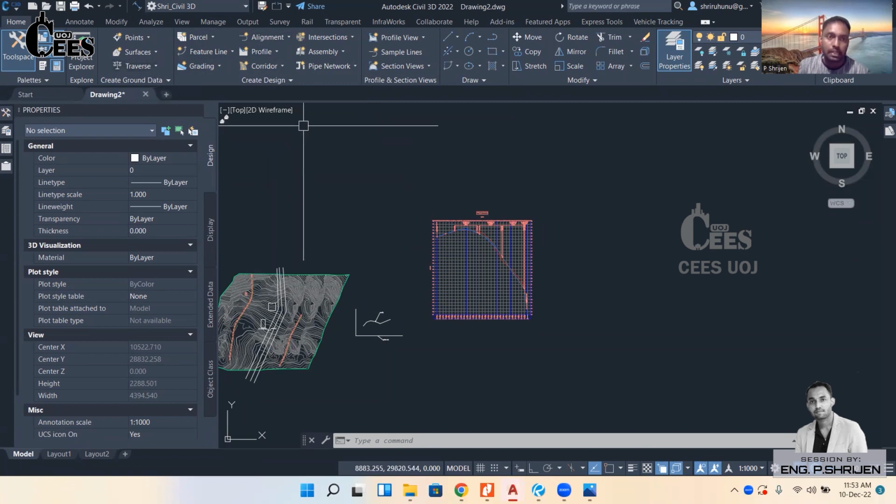By using the survey editor, the traverse works and gives the information by point. By using these tools, we can get the misclosure error. Using this misclosure error, we can easily divide that misclosure error to each and every point. So Civil 3D makes our civil engineering lives a bit easier.